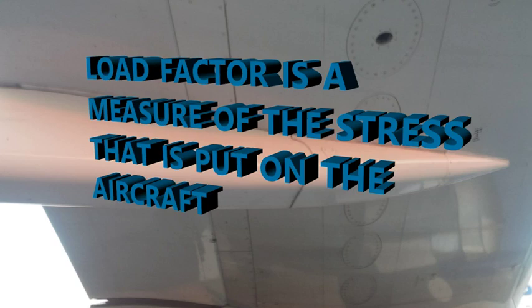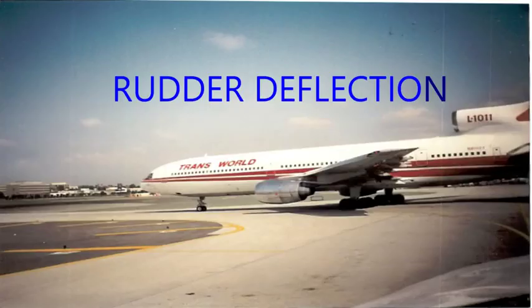All right, what about your rudder deflection? Very important with rudder deflection. There are max ranges, obviously. If you've worked on airplanes before, maybe you worked with the rudder limiters. I talk about that with the DC-9. The limiters are there to protect the rudder from exceeding its mechanical range. But should we really rely on that? I mean, they're there, it's good. But the pilot can actually push the limit. He could push beyond if he wanted to.